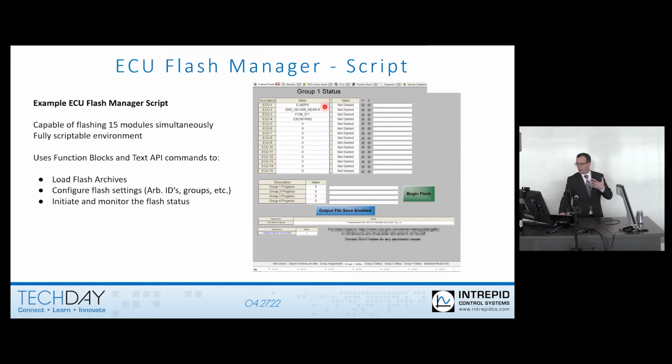It's going to load the ECU name, and this is on our graphical panel. If you guys aren't familiar with that, this is our custom scripted page that we use in Vehicle Spy. It shows us the status, and then we've got progress bars and a pass/fail LED. This is all a custom designed user interface. Then you'll also see at the bottom, this is scripted to show the progress of the groups. It automatically updates, shows the groups at the top as they're going, and shows you where you're at in the big scheme of things.